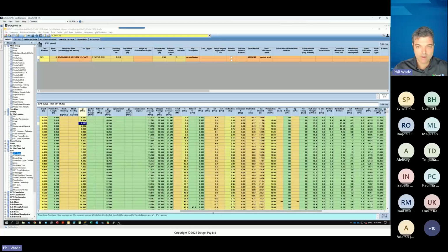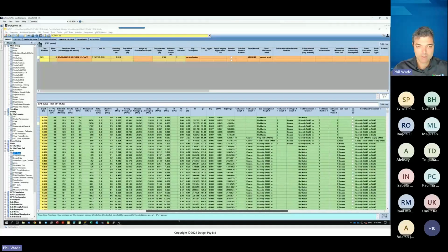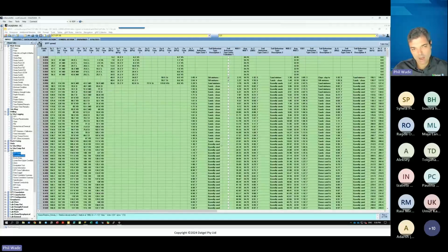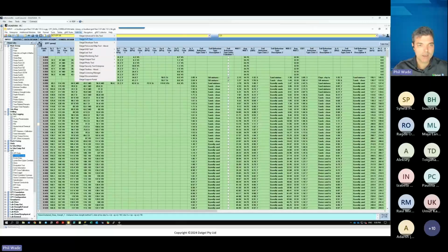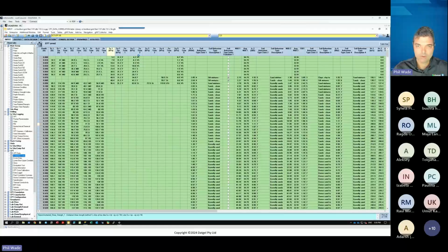So we can see here that there's a lot of calculated fields for CPTs. So behavior types and other derived parameters. And on the correlation data table, we have the correlations, most of the correlations, there are more elsewhere. And we can see down the bottom here has some definition of what is the formula, though this isn't truly the formula that's used, it's more like just a hint caption. The actual formulas are defined in the Datgel formula tool. Now this is going to take a little bit of time to load because there's a lot going on.